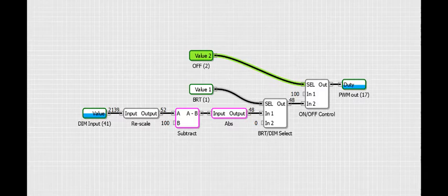Right now, the input is in the on position, and because it's green, as you can see here, it is selecting input number 2. If it was a 0, in other words, the switch was off, it would be selecting 100. The reason that it selects 100 is that, due to the inverted pulse width modulation, 100 is equivalent to the display being completely dimmed or off.